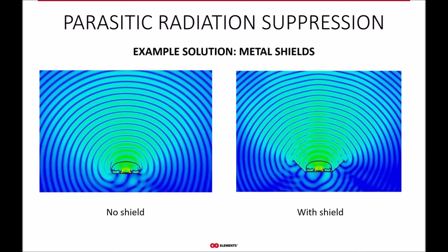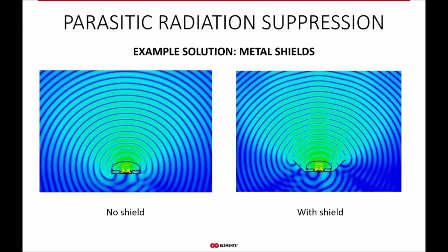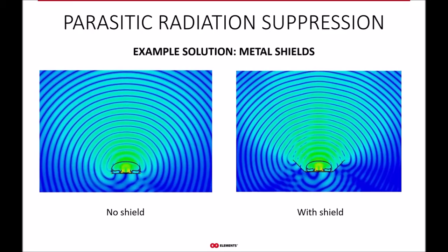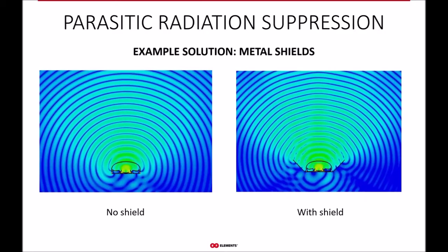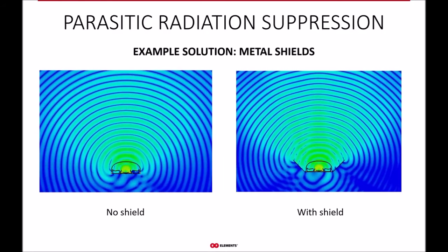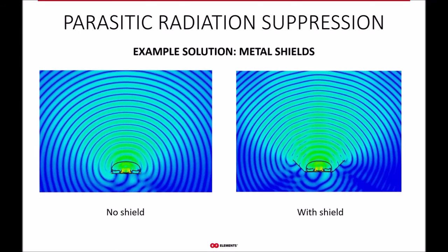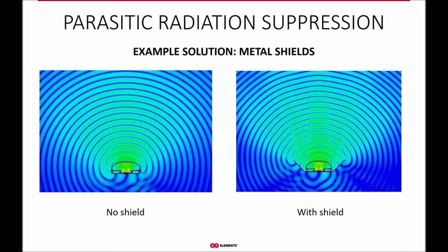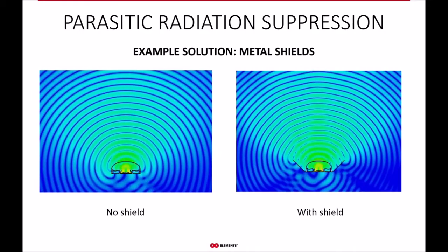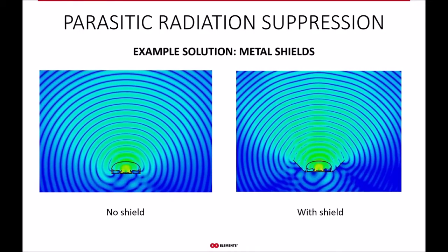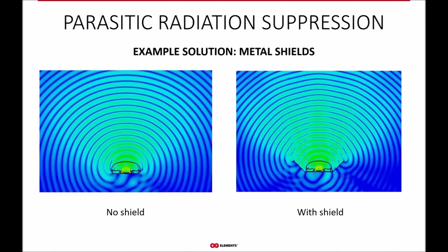While the shield might help improve the front-to-back ratio a little bit, the azimuth side lobes they aim to suppress are actually still strongly present, as we can see from these near-field plots. On the left side is the generic patch array antenna when we're looking at it from the top. And a lot of radiation finds its way in the backward direction, causing the side lobes that are harmful to WISP networks. And on the right side is the same antenna, but with the shield, which you can see as the 2 slanted lines at the edge of the antenna body.